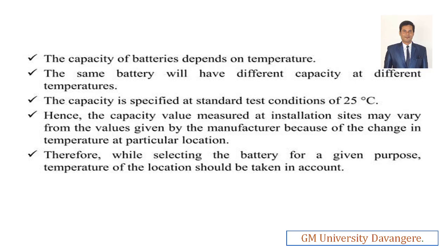If we carry the battery to different regions, we'll have different temperatures. Based on that, the charging and discharging will also make a lot of impact on the batteries, right? Because if you take the batteries to other regions like Shimla, where the temperature is very low, the degradation of the battery will also make a lot of impact on the battery health. So that's why you have to focus more on the temperature conditions.